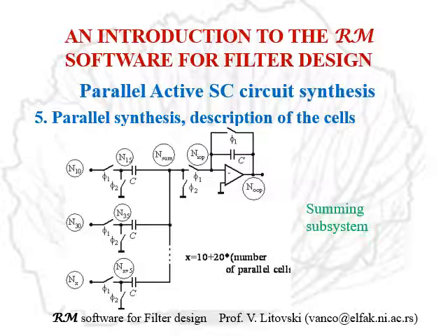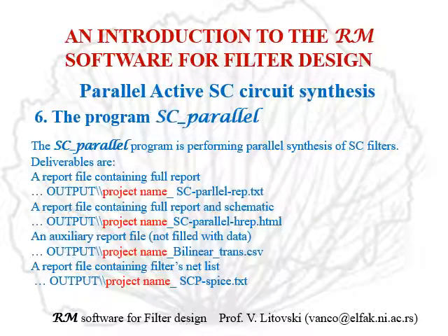the sign of the summation, or the weighting sign of the summand, may be controlled by simply exchanging the controlling signals of the switches. Instead of phi 1, put phi 2 and vice versa. That simplifies the summing as compared with the case of RC filters where separate inverters are needed. And that would be all about the structure.